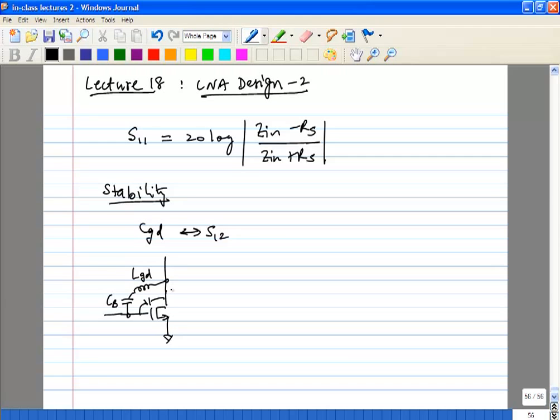The thing to remember is, as we know now, these inductors have parasitic capacitors. You have capacitors which have bottom plate capacitances, parasitic capacitances. So all of this will load your input node. And obviously the second thing is, we're not even talking about the area, right? You saw that it's 200 microns by 200 microns. It's just huge. You can't afford to add an inductor anytime you want. So this is the first way, tune out your CGD.